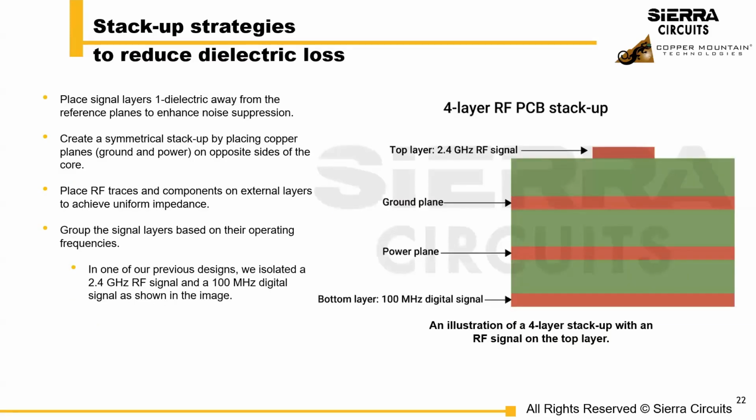Some stack-up strategies to reduce the dielectric losses. So first, place your signal layers one dielectric away from the reference plane to enhance the noise suppression. Position your RF traces and components on the external layers to ensure consistent impedance. Finally, group your signal layers based on operating frequencies.